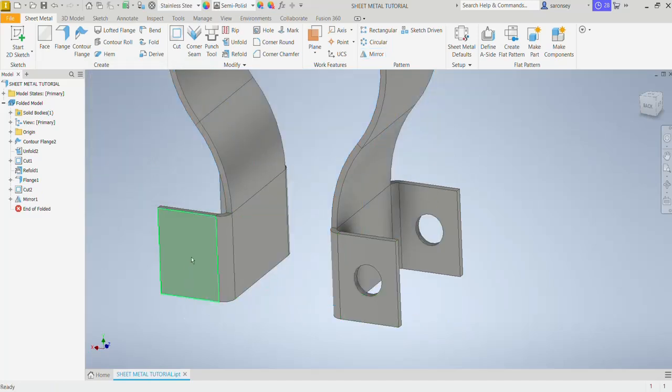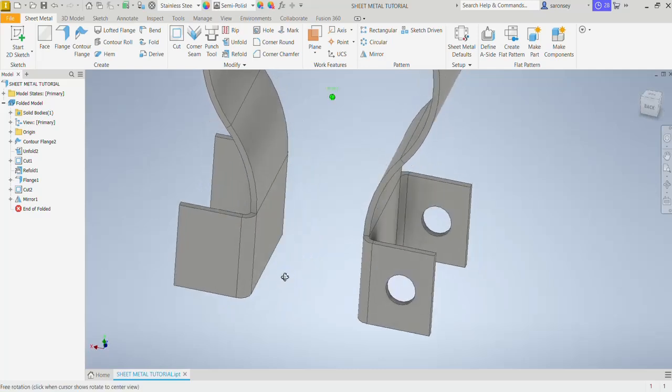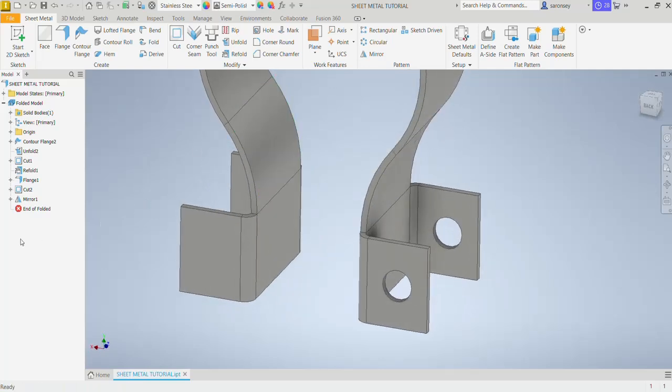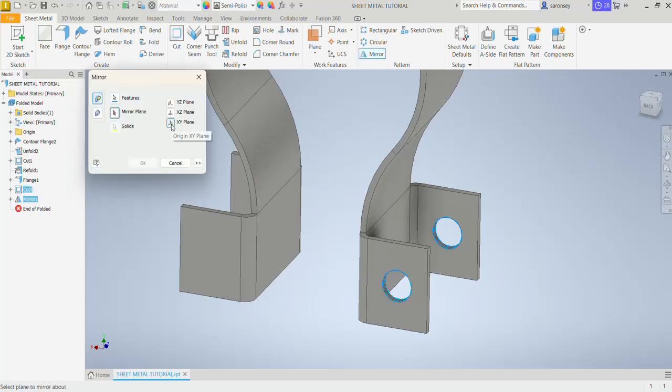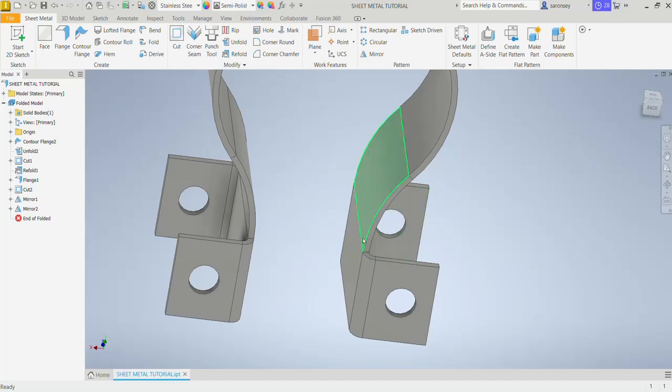These holes are also seen on the other two flanges on our left. Let's mirror again to get them over there. So we'll select our two, first the mirrored hole and the initial one we did, the cut, and mirror them. Let's choose our mirror command again and select the plane we want to mirror across. So you choose the YZ plane, press OK, and there we go.